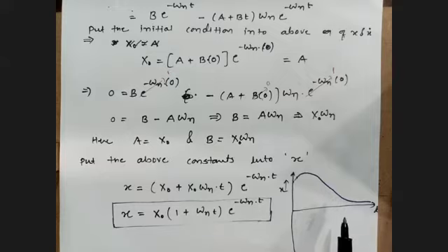It is just like a hydraulic door opening and closing. In our classroom doors, there is a hydraulic system, right? Once you open it, it quickly comes near to the equilibrium, and then it takes some time to close fully. So this kind of hydraulic system has this type of critical damping behavior. This is what we call the critical damped system.